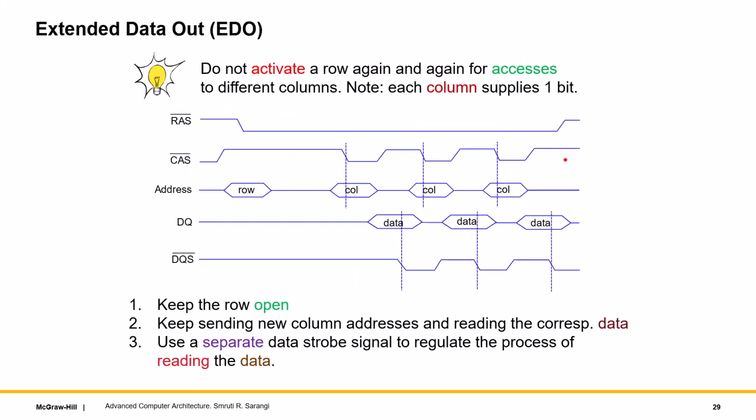So we can make this process slightly more efficient. So accesses have spatial locality. Once a row, so a row incidentally in the DRAM is called a page. It's not the same as a virtual memory page, but row and page in DRAM are the same, and that's maybe, let's say, 2 kilobits for every array. So that's a fairly big thing. Across all the arrays, it's a lot of memory.